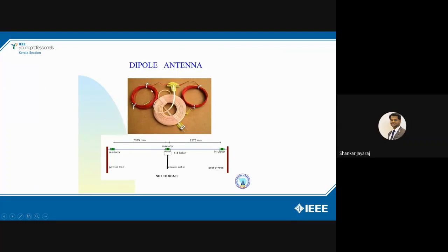So I have around 20 meters here. Similarly, this also I will put on the straight side. So now I have 20 plus 20, which is 40 meters, right? With an antenna of 40 meters, we can operate in HF frequencies. So you need to have this big antenna. For an antenna, it's not mandatory that it's a thick rod. It can be a radiating element.